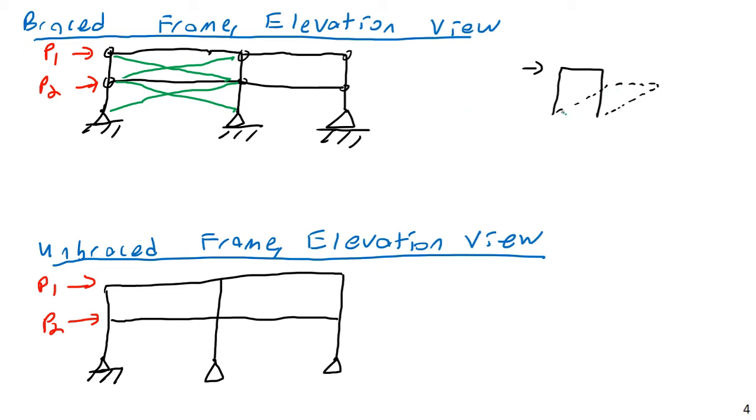See, the reason that this is so weak is that this frame can lean over without actually deforming any of the members. None of these members have to go into substantial compression or tension in order to tip it over. They can just change their rotations. But the moment you add bracing to a pin frame like this, if this thing wants to flop over, it cannot without putting one of these members into either tension or compression. So that is what allows you to use pin connections for everything. If you're going to do that, though, you have to add braces.